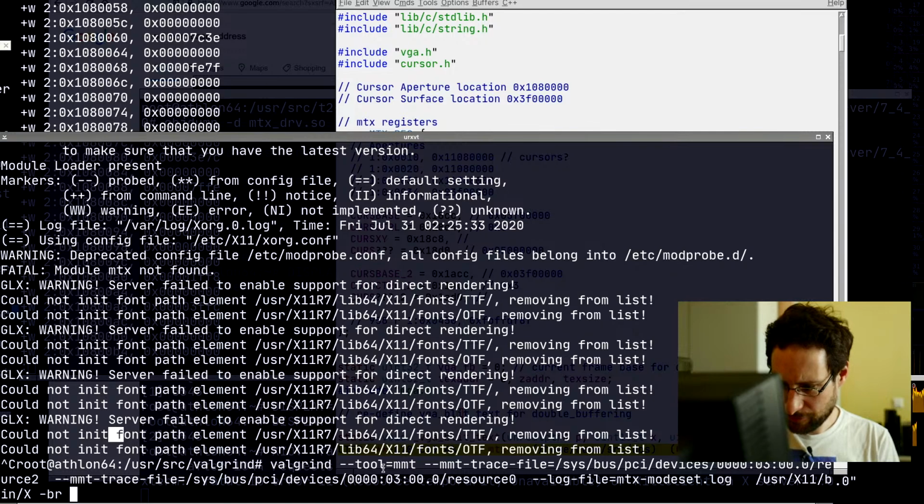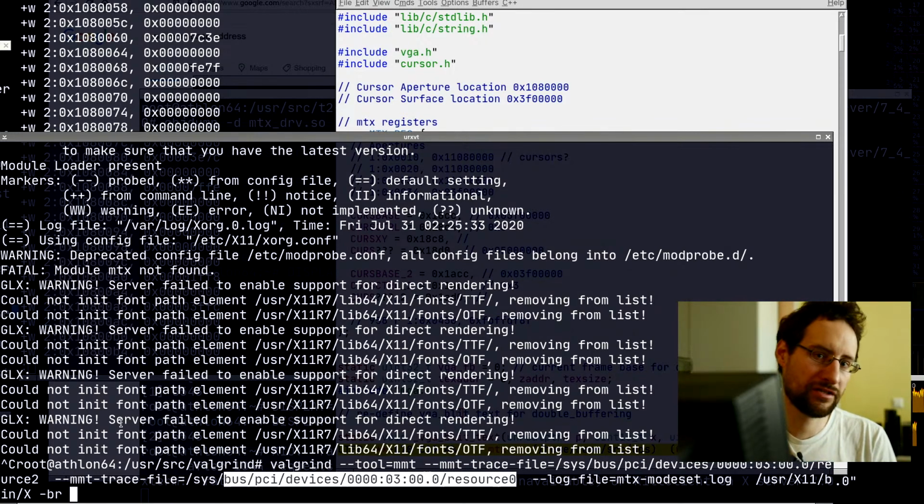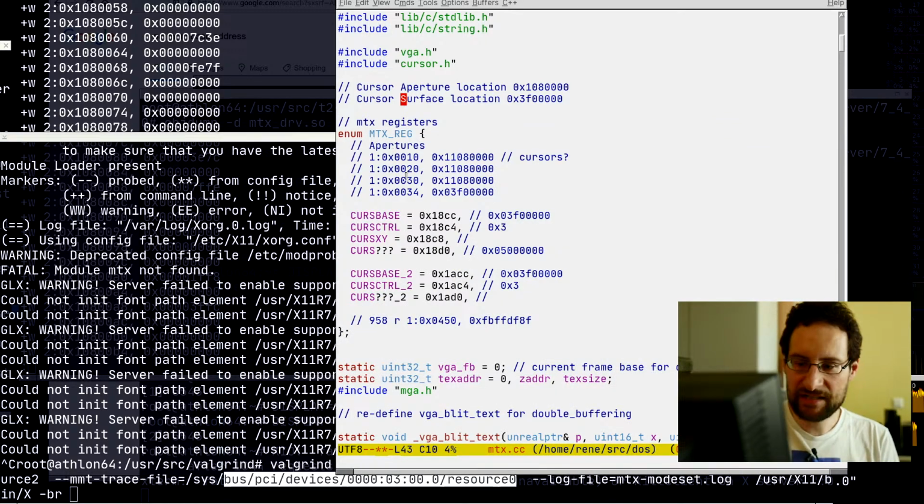So either memory mapping this bus PCI resource 0 or resource 2 ourselves, or /dev/mem, like I've done for the Lynx 3D, where I've written a full 3D engine control stuff. And so writing this handful of registers and double checking that what we have deciphered here works like we thought it would.